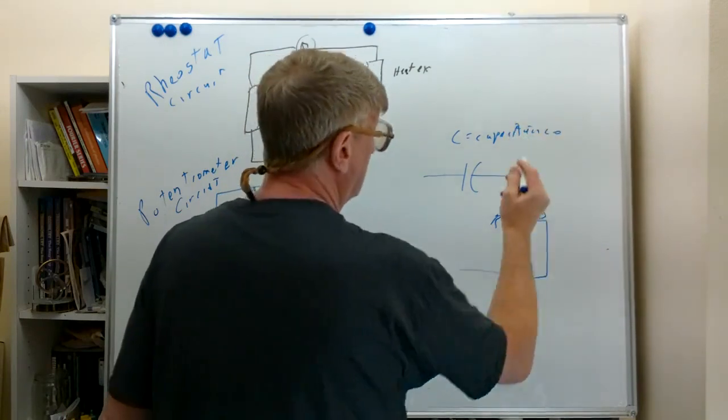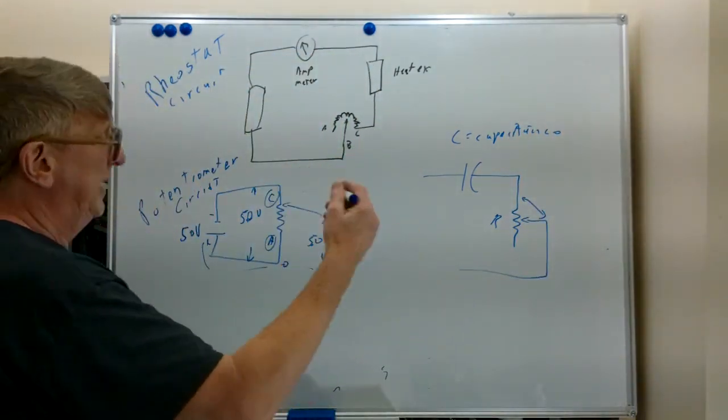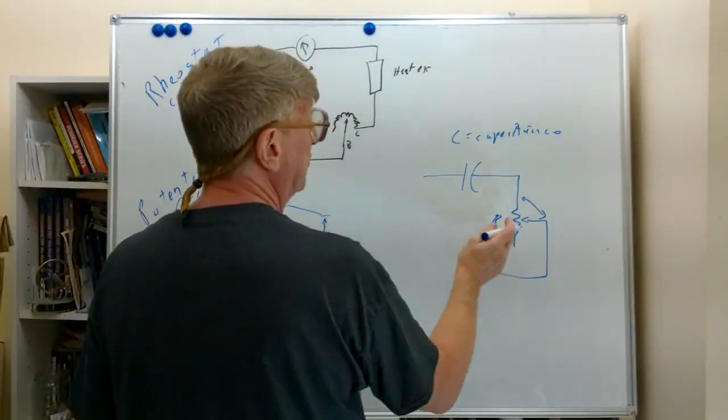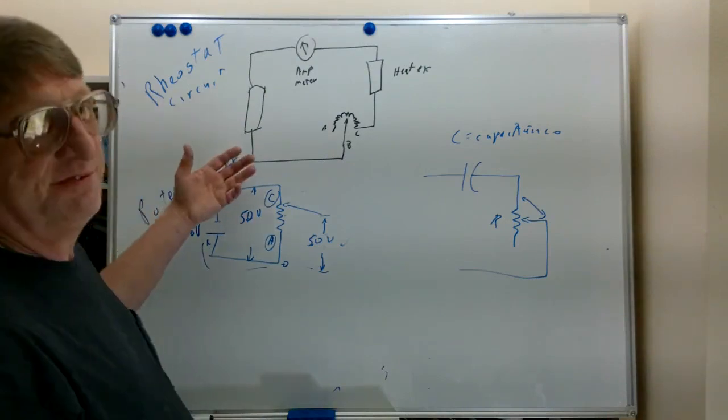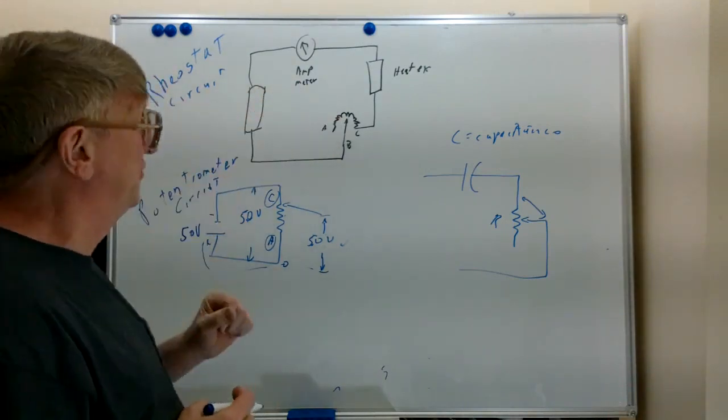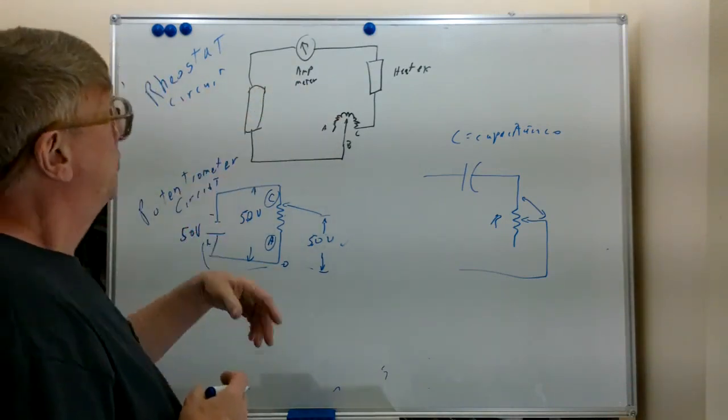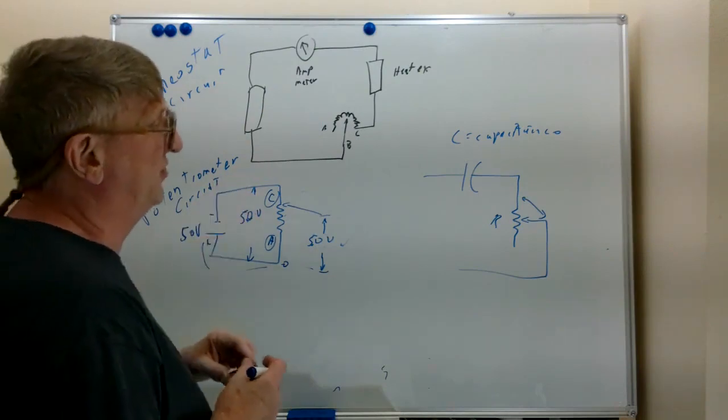So that would be the case. We're using a potentiometer as a rheostat because we're interested in the resistance. So the technical difference: rheostat, you're interested in resistance. Potentiometer, we're interested in tapping off part of a signal.